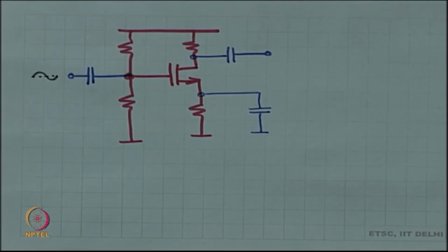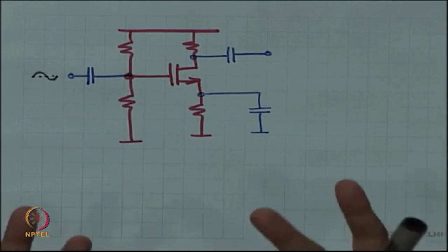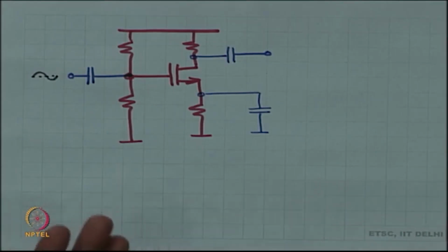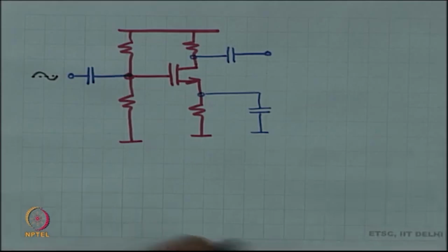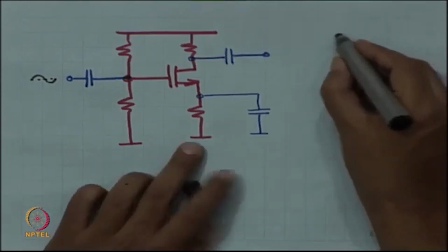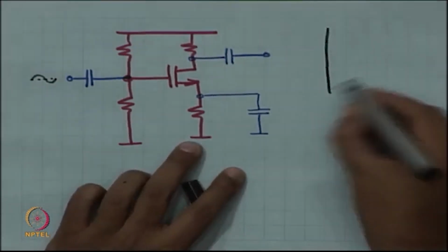Now, this MOSFET has to be kept in its flat region of operation, otherwise what? Otherwise the basic understanding of the MOSFET, the gm for example, no longer is what it should have been. The MOSFET is no longer going to reside at the nice operating point that you had set.